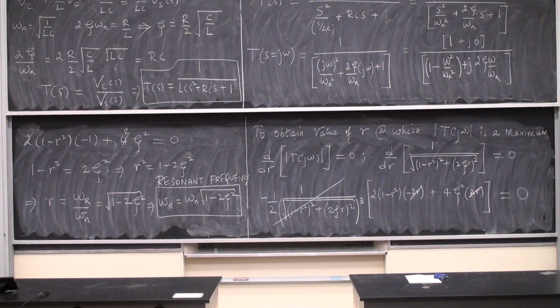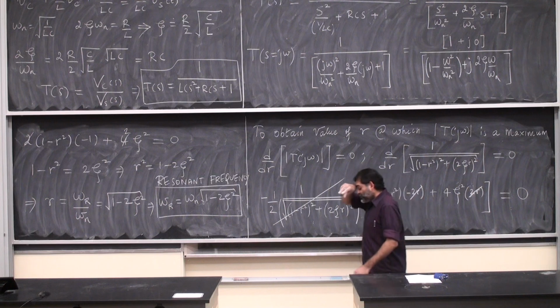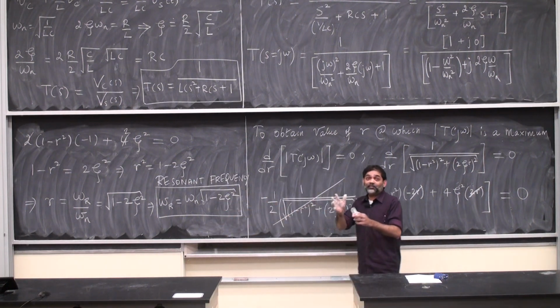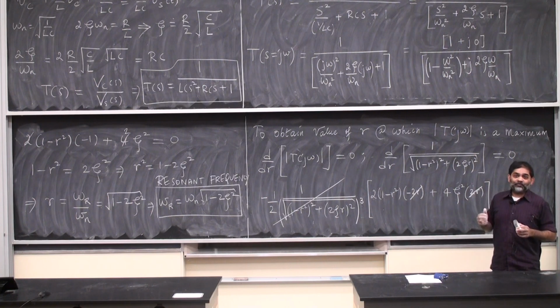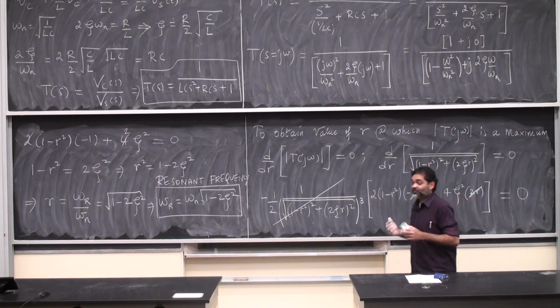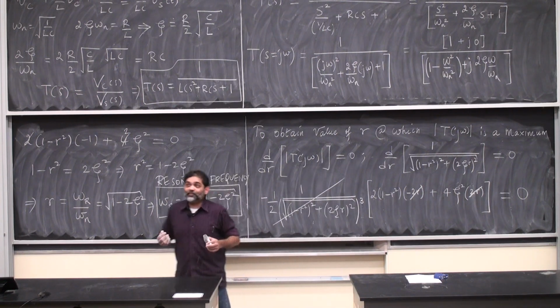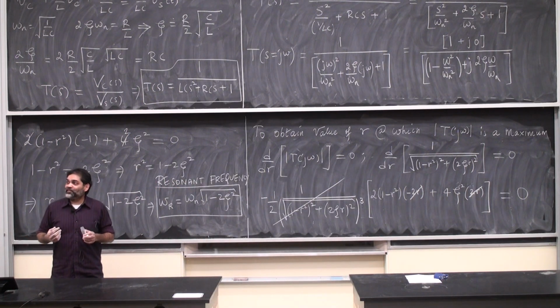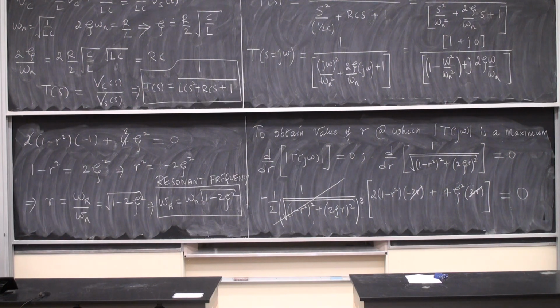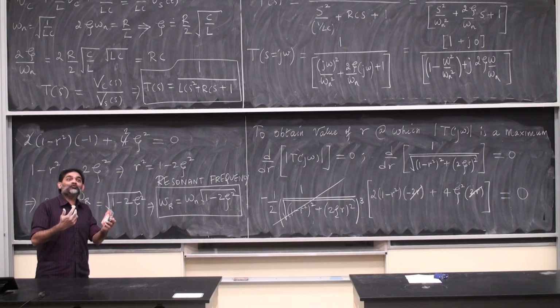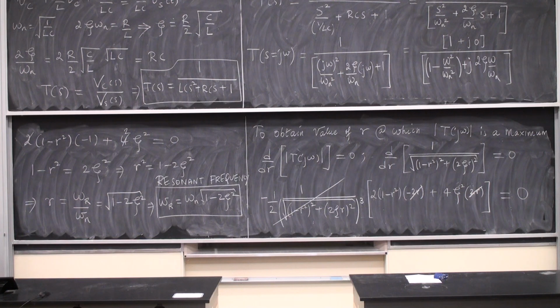This has great import for us because the resonant frequency, and you're going to see this in a second, is the frequency at which the magnitude of the response is the largest. So perhaps a foolish designer will say, get rid of damping, damping is screwing me. If I get rid of damping and then calculate the peak value of the frequency response function, it's going to blow up, it's going to give me infinity at the resonant frequency. You're going to see this. I'm going to wait until everybody has all the details down here, and I'm going to pull the top panel down. I have a couple more things to do before we quit today.